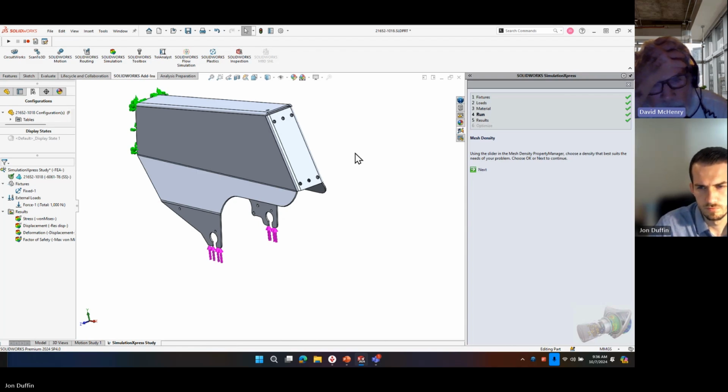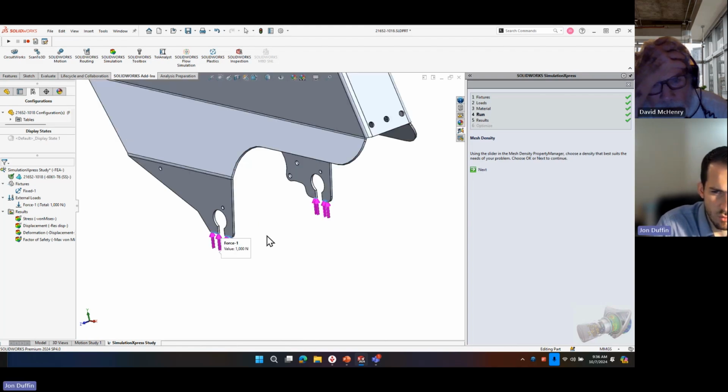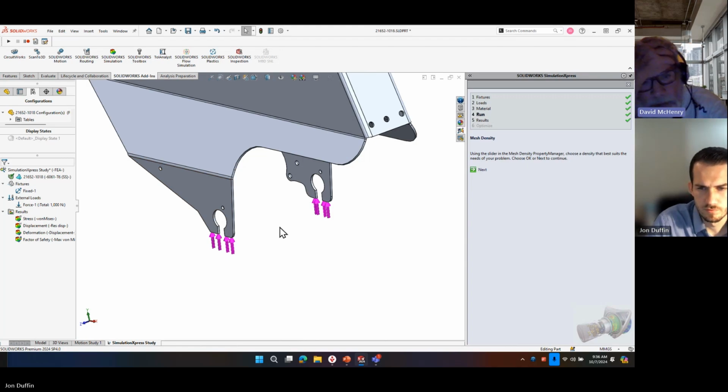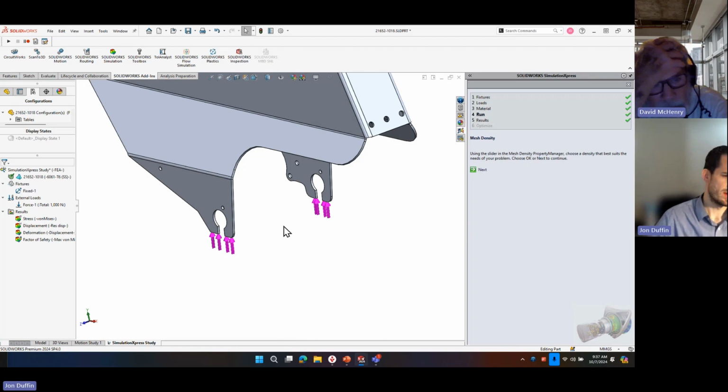The way the fixed side works, if you put multiple surfaces on the fixed side, they're all welded together and don't move relative to each other at all. One interesting thing you could do is swap those. But I'm asking about one load that's kind of distributed over all four surfaces, so those four surfaces can't move relative to each other, because right now the way it's doing the split, it wouldn't do that with the axle in the hub of the wheel.